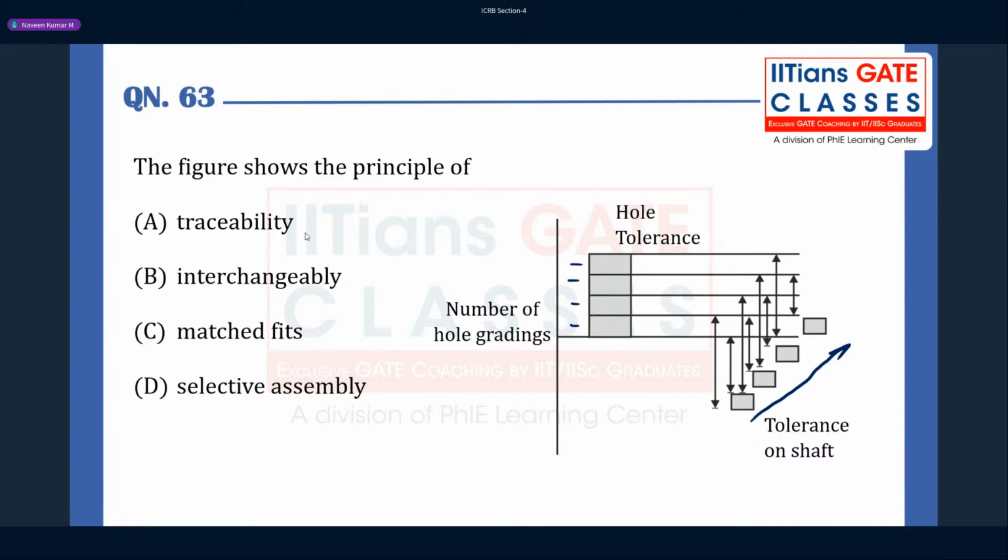If you want to understand how reliable that equipment is, see, you have manufactured some item. Let's say somebody told you to manufacture some billet of diameter 26.2, with some plus or minus tolerance, 0.2. You made it right, but if there is a problem with the measurement device, it will show you wrong. Then you feel that you might have gone wrong, and in the inspection you will reject the sample. That is not good.